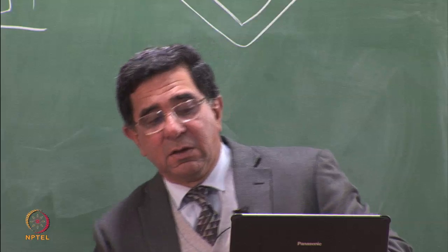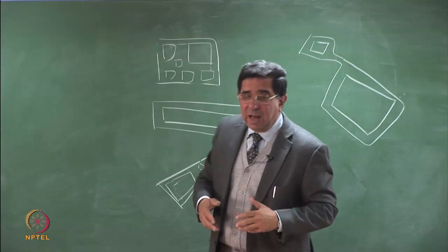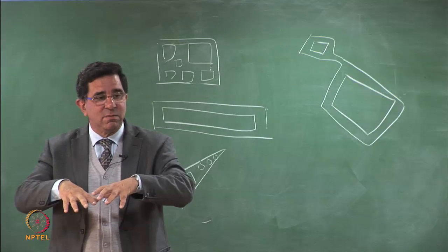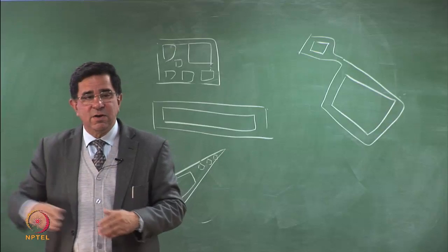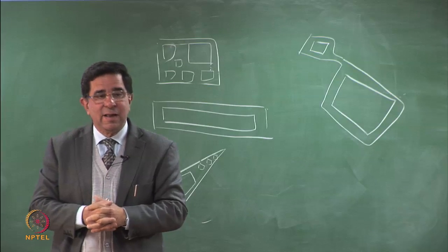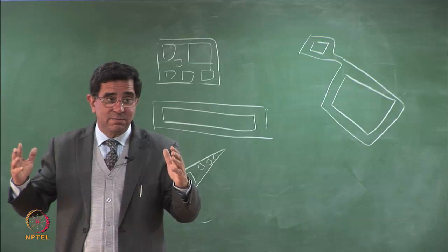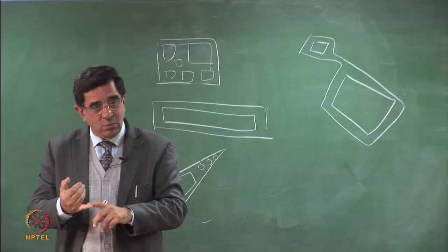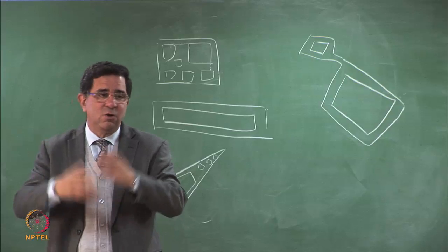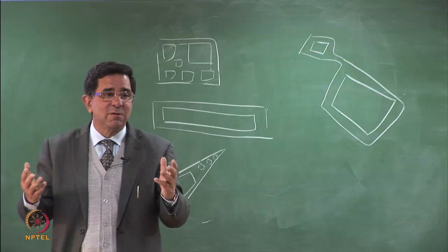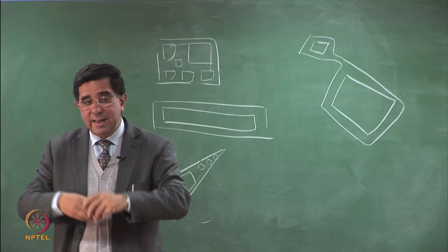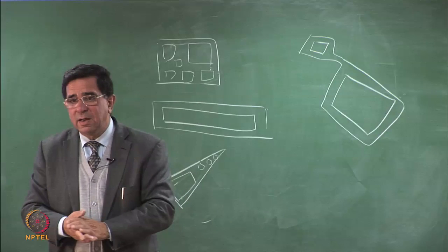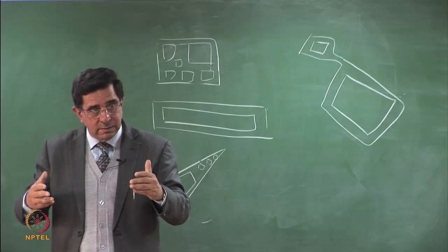So I have shown you in the last few minutes what landfills look like when you look at them from the top, and what they look like when you slice them open. You've seen the sections, they can be very variable. And we said topography, depth to groundwater table, and depth to bedrock. If both are high, you're going to be above the ground. If you have sloping ground, you can only make a sloping or a valley type of landfill. And the area, the planar view, depends on what area you get. You can't decide what type of area that you want.